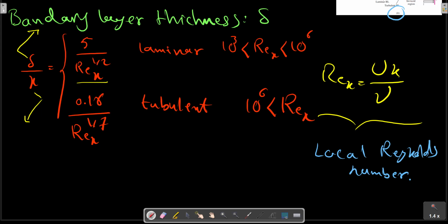Various calculations can be made from this formulation, for example the boundary layer thickness for low Reynolds number. It depends on the Reynolds number magnitude. For a slender body such as a plate with a force parallel to the oncoming stream, we conclude that the assumption of negligible interaction between the boundary layer and the outer pressure distribution is an excellent approximation.